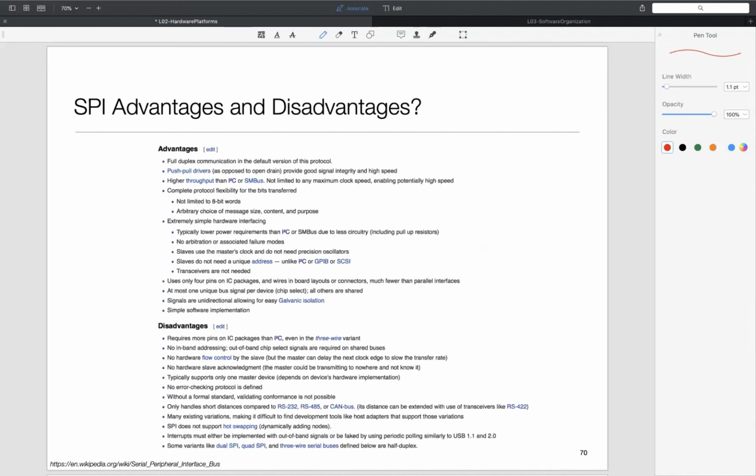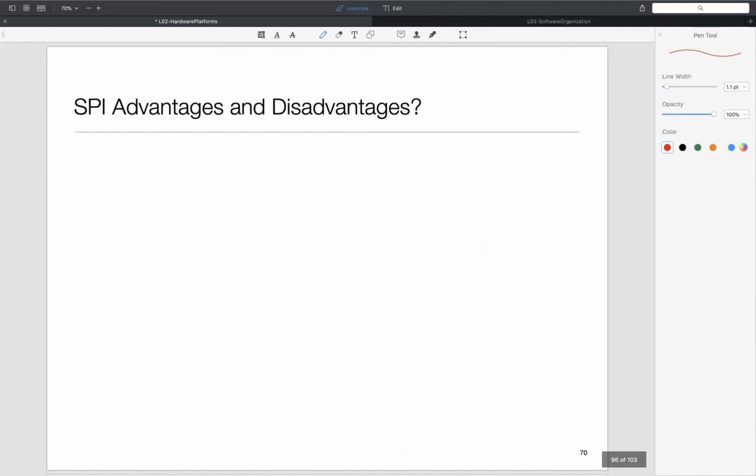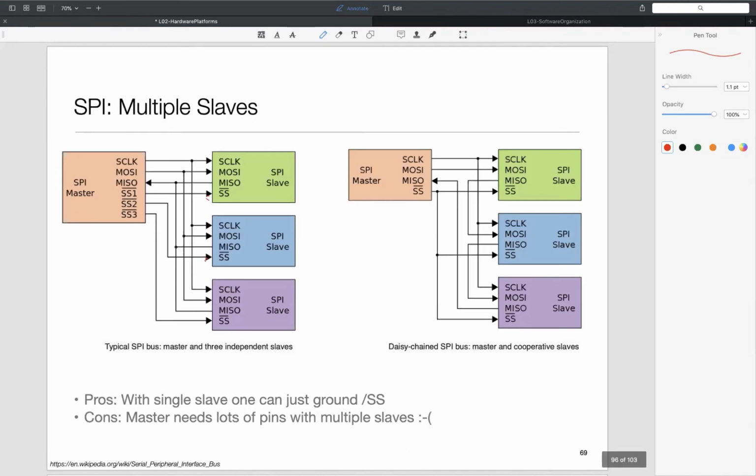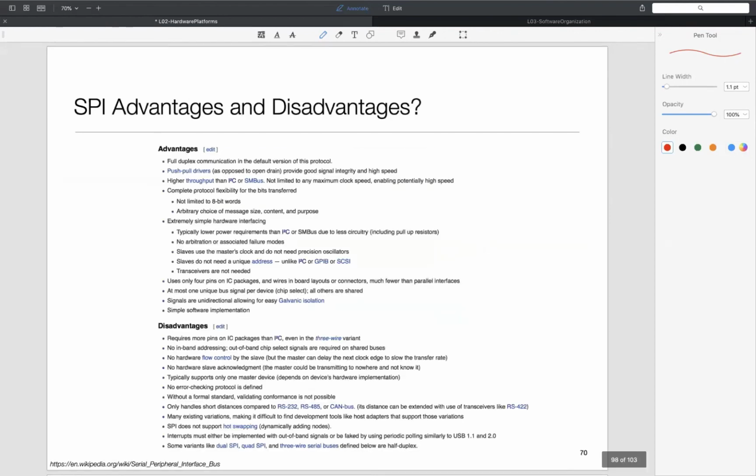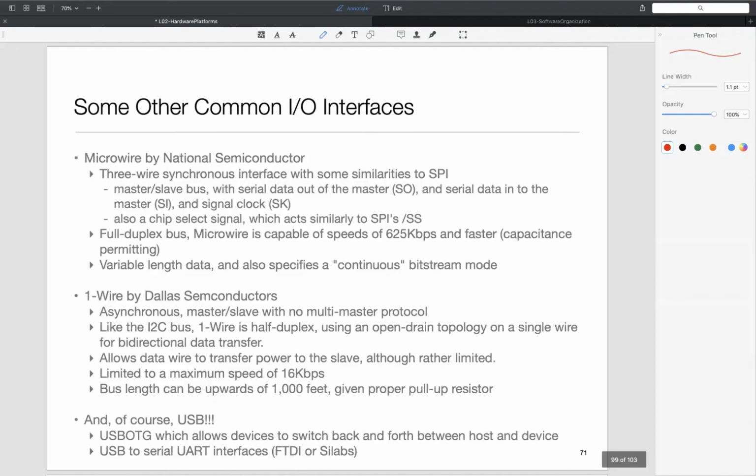It doesn't allow explicit addressing within the signal. Okay, there is also no flow control. Flow control refers to what if one master is sending the data and the slave is not able to read. So there is no stopping, like you can't say wait for the data. Whereas these flow control signals exist in other protocols. So there's a whole bunch of trade-offs that exist between these things. Again, I2C is probably the most sophisticated of the lot, and you would see a lot of peripherals using it.